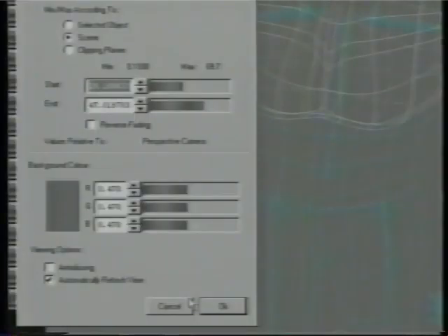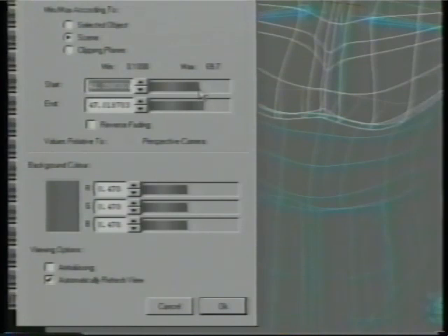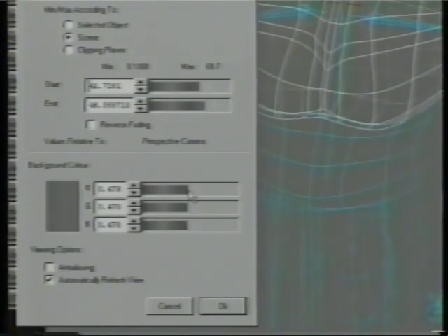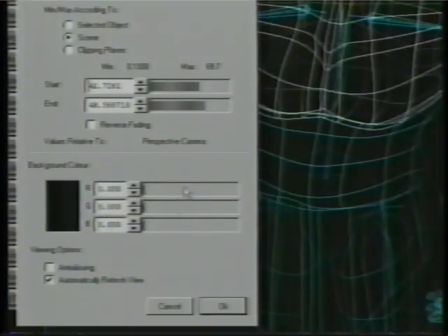And we're in depth queue mode here, located right there. In the depth queue mode setup box, you have a couple of options. This slider is to determine when the fog begins, and see it's behind the camera now, and then you can set it to begin after, so it becomes bright. And if you set it very short, you can see how you can control the depth of that, and far away then it will look just like wireframe. And I like to set it to gray here, but normally you get black.